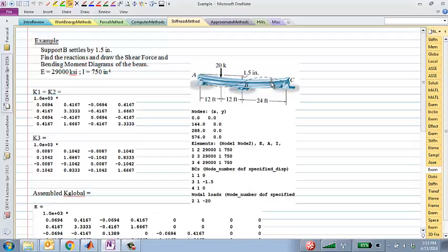So keep in mind that if you go out to your first job and you're modeling some structure, and you have to choose a number of elements, if you choose too many elements, then you will bog down the computer. If you choose too few elements, your answer might not be accurate enough. So you have to do a little bit of a balancing act there. But for this particular problem, yes, at least we need these 4 nodes.